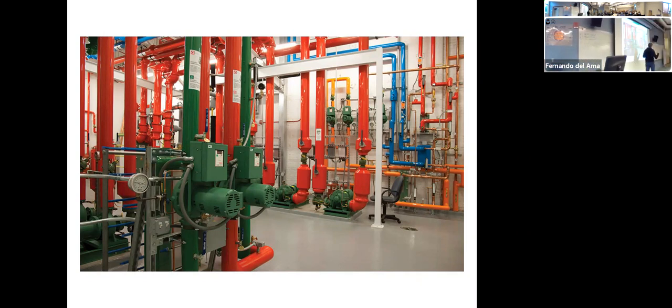Those are mechanical rooms, but now, again, we have abstraction: a circle and a triangle. This is a pump, but what is a pump in real life? Something like this. And that's interesting, because you see that here we have two parallel pumps. When the building is really big and we can't afford having a building without water or without a heating system, because it's a hospital or whatever, we always have two parallel pumps. So we have something like this.